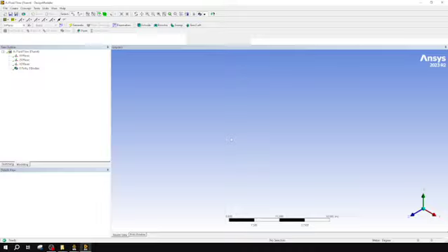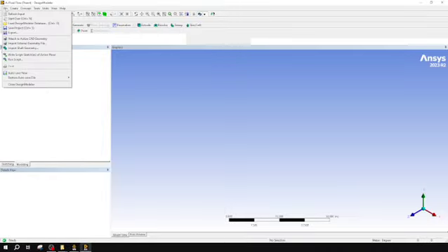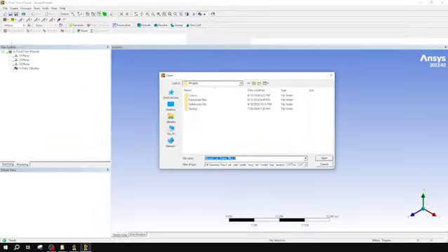One of the things I'm expecting is that I already made my models out in SolidWorks. It's the CAD software I'm most familiar with. So I'm going to go ahead and import one of those models. To do that, going over to File, Import External Geometry File. If you used an ANSYS software CAD file, you can do this Attach Active CAD Geometry. But I used SolidWorks for mine, so I'm going to want to import an external geometry file. Now, where did I save that again?